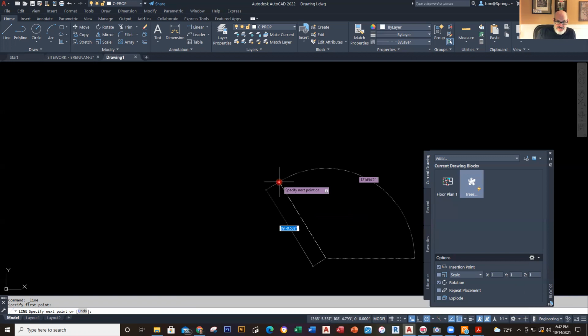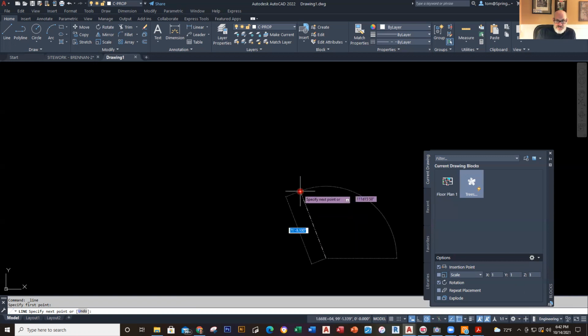So I typed in, did I type that in yet? I don't think I did. So 48.92 feet less than. And the less than is, I hold the shift key down and I press the comma. And now I have to put in the direction, which is going to be N17D, 30 minutes, 9 seconds west, like that. So I hit my enter key, boom, and I got that.